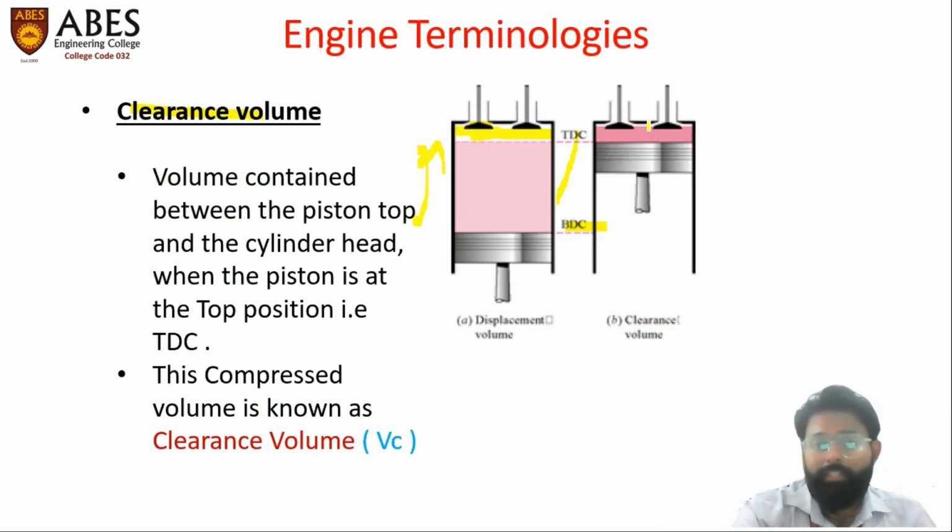and the cylinder head. So between the piston and the cylinder, a particular gap or clearance is provided so that the piston should not strike the valve and the head every time it reciprocates. So to avoid the striking of the piston, we provide a certain gap. And this gap is also useful for us to store the compressed charge, the air and fuel mixture, after the compression stroke. It gets compressed within this volume. So the entire compressed volume will be in this clearance volume.